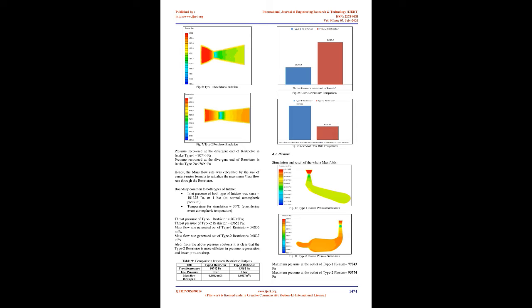Now the resonance frequency was found by Helmholtz resonator theory. FH equals C/2π times the square root of S/(V x L), where FH equals resonant frequency for the max torque oscillation of air wave. C equals speed of sound equals 340 m/s. S equals area of the runner equals 1520.5308 mm².